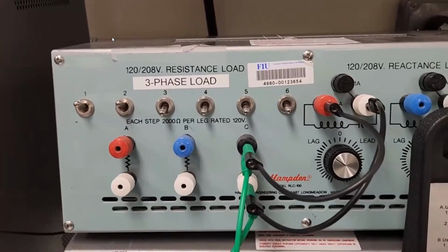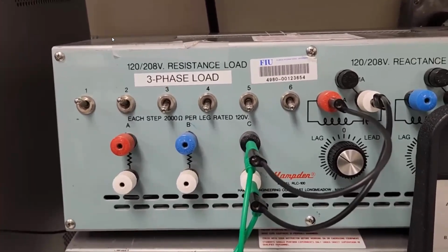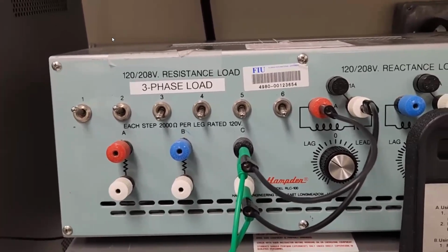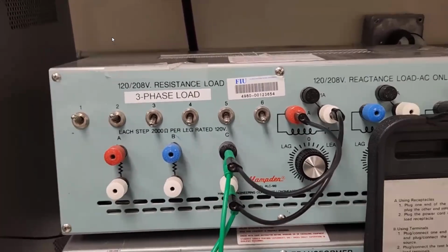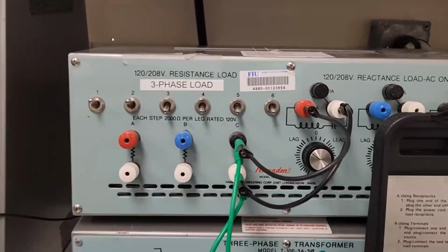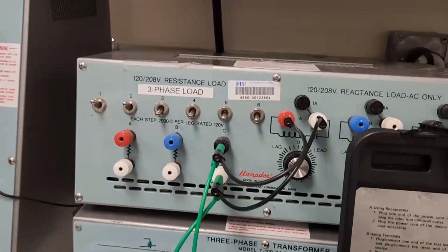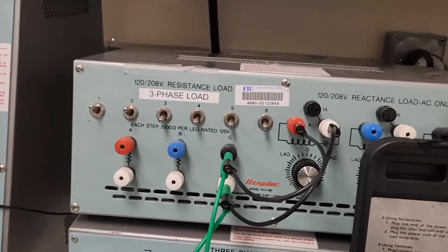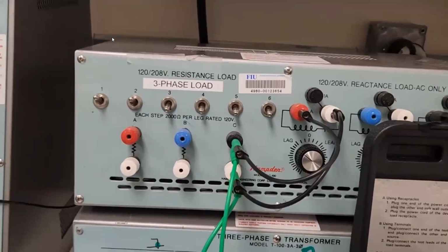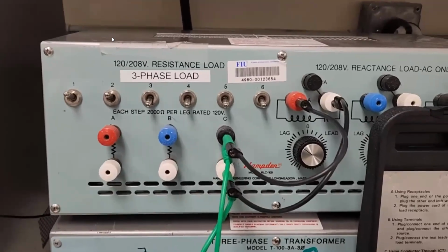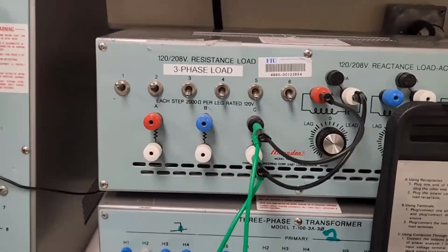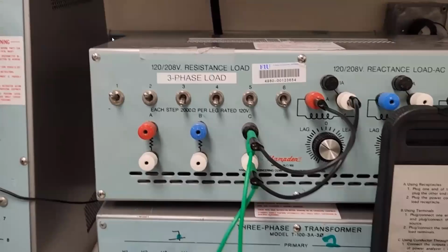So the smart way to do it is to use capacitance across the loads, which we call a power factor correction panel. It's normally connected in the utility section of any house or any residential loads, or if the load is too much. In residential loads, normally we don't put it. In some cases we do, but in most cases in industrial loads we use capacitor banks as power factor correction panel near the utility section.